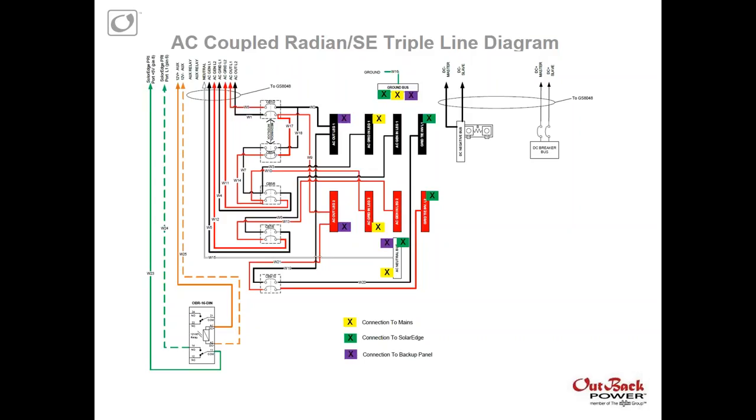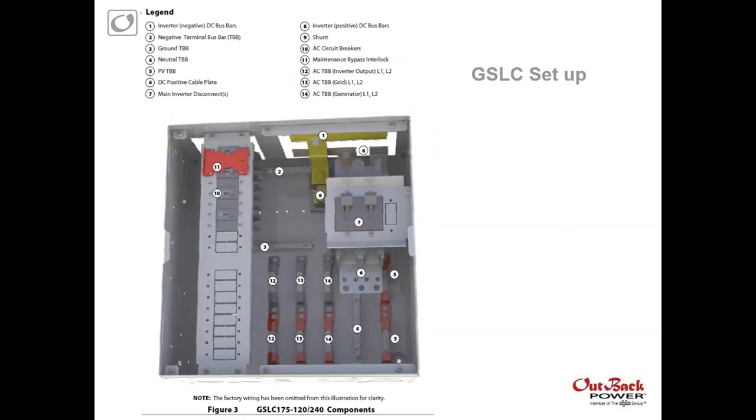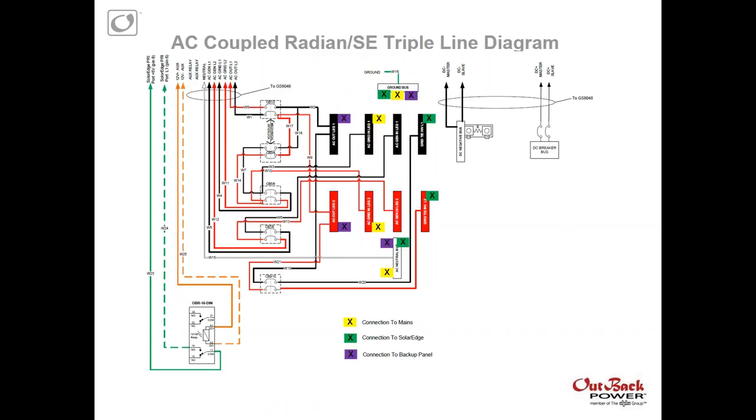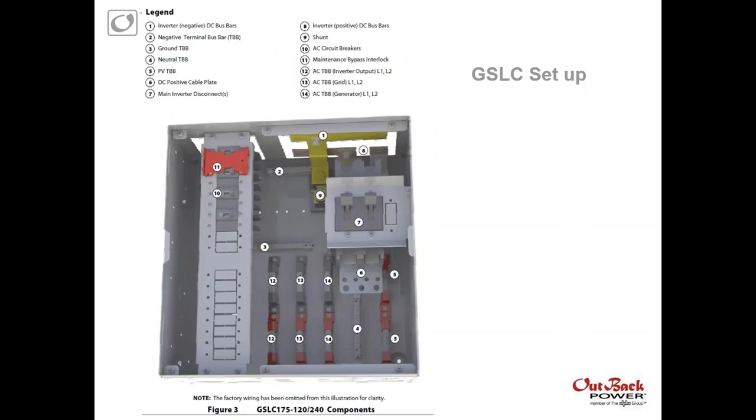the SolarEdge. In this case, instead of just opening a relay and dumping that power, what it actually does is it controls the power reduction port, and it takes it from 100% down to 0% on the timeline that SolarEdge likes to see when the power is turned off in their inverter. Now, if we go on to this next slide, you can see that this is essentially what this is pictorially.